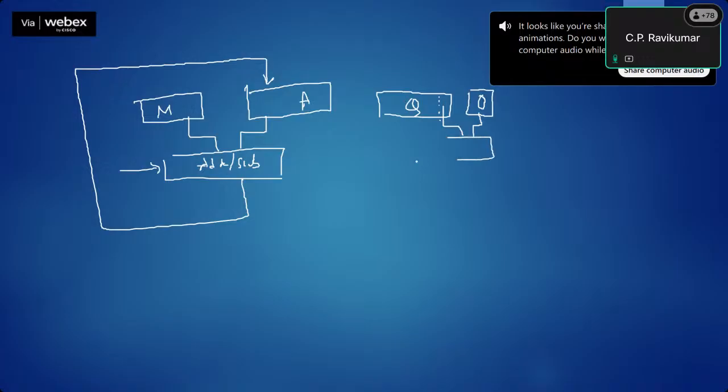So these two can be either 00 or 01 or 11 or 10. In the 00 case we shift. In the 11 case also we shift. In the 01 case we subtract and shift. And in the 10 case we add and shift.